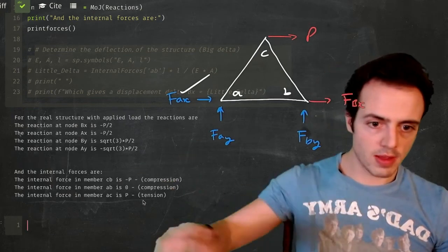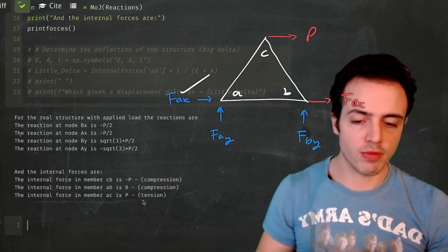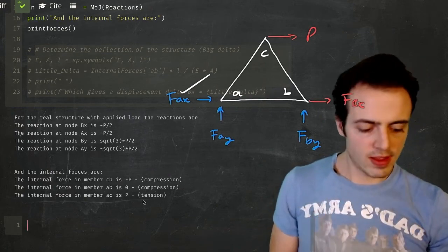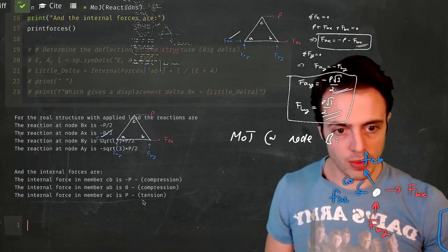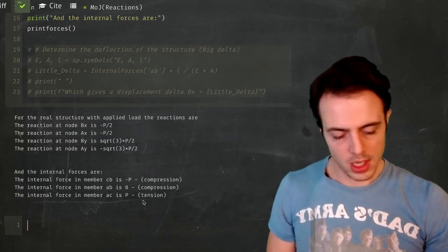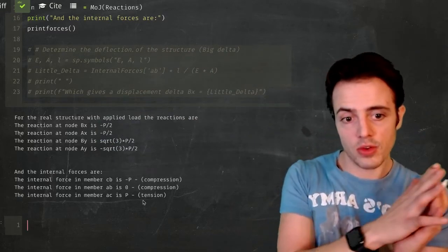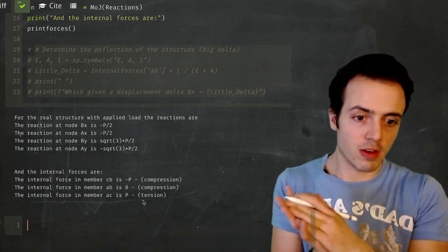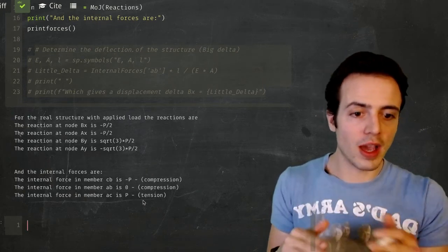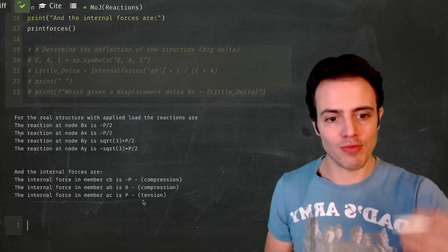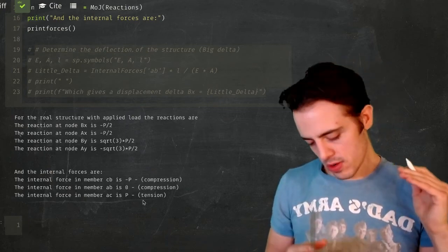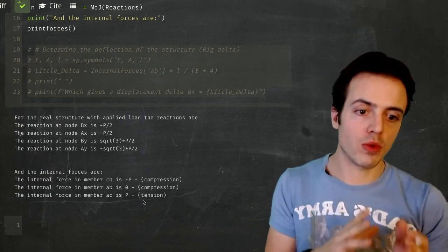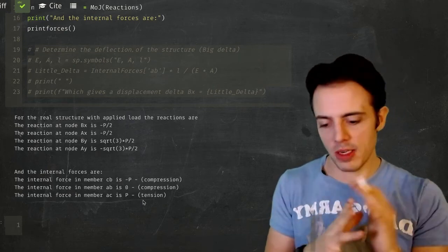So this is how we go through and how we use the force method for a structure like this. This was relatively simple to do because we were able to see that with this structure, the displacement of the node at which we had the redundant reaction, in the direction of the reaction, was aligned with the extension of a member, and that's what made it really easy. For even ever so slightly more complicated problems, it becomes quite difficult and cumbersome to determine deflections.